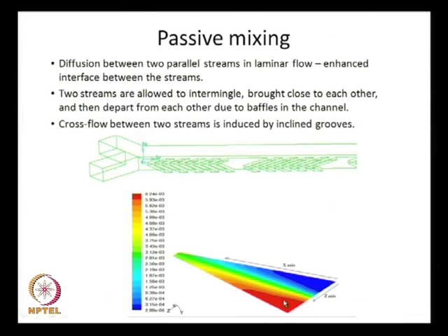Now, this is a typical concentration profile that you see here. This red and blue color, these are two extremes, say concentration in some unit. Blue, extreme blue represents 2.88 x 10^-6 here, and 6.2 x 10^-3 there. So, these are the two extremes and they are going through the inlet. This is the inlet, half of it occupied by red and half of it occupied by blue, and as it flows down you can see that it is getting mixed and at the end of it, it is coming almost green, which is halfway between the two concentrations.